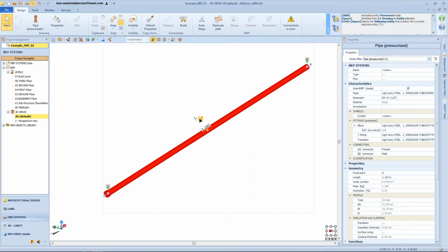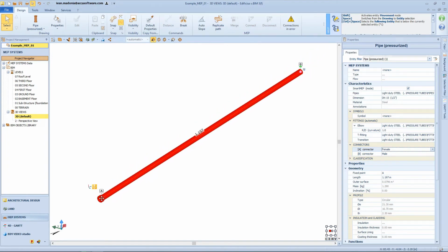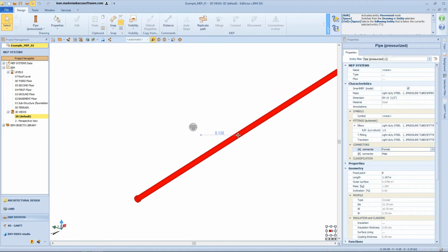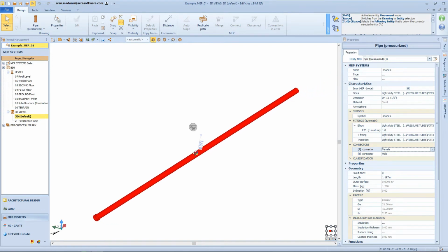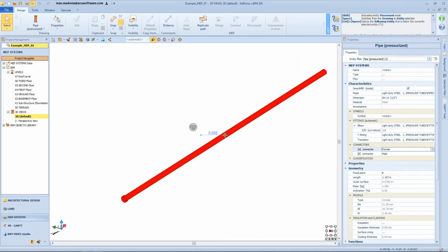The anchor allows you to move the pipe rigidly in 3D space. By clicking on the orange circle that identifies the node on which the anchor is positioned, the pipe snaps to the mouse cursor and can be moved in 3D. At the same time, a ruler icon and a blue arrow appear on the screen, with the origin point fixed at the previous position of the orange circle, while the other end follows the displacement of the pipe, whose distance from the initial position is dynamically reported in association with the arrow.